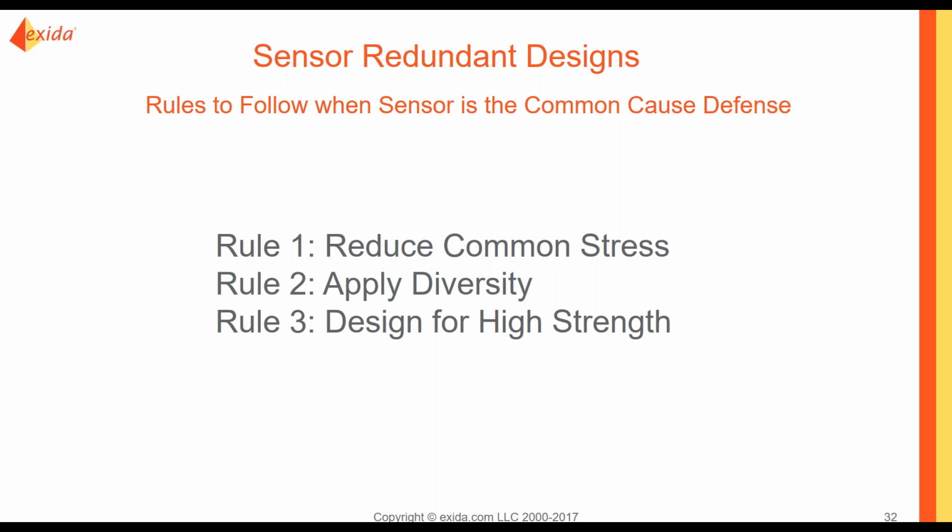That is one of the reasons IEC 61508 requires more stringent design and testing procedures for higher SIL levels. Sensors with systematic capability of SIL 3 or SC3 are more suited in redundant designs, even with identical redundancy.